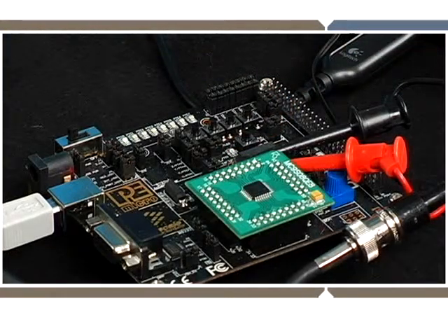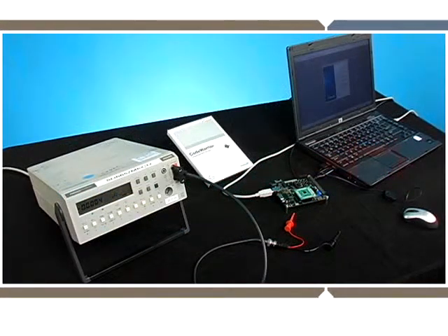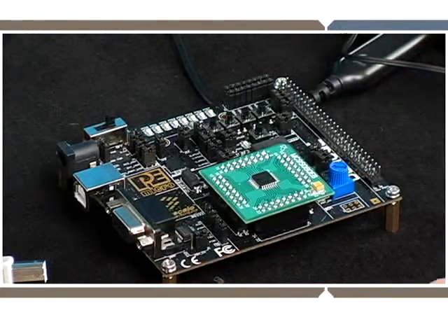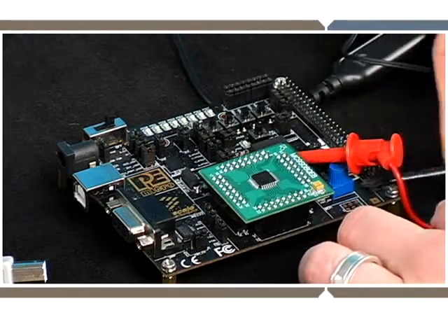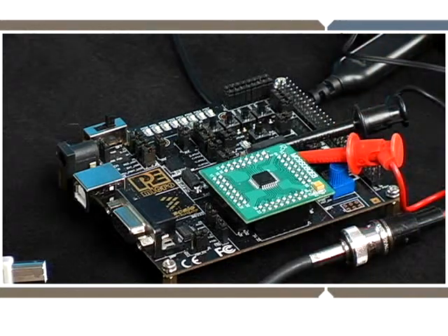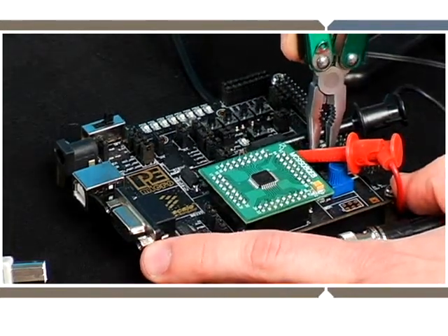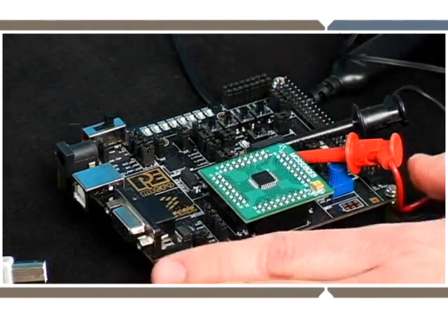So before getting started, let's get our board set up for the lab. My board is currently in the default out-of-the-box configuration. The first thing we'll need to do is remove jumper 17 and attach our digital multimeter to be able to measure average current consumption. Next, in order to use our external crystal oscillator, we'll need to remove the 2 jumpers at J20 on the board. These jumpers utilize a multiplexed function on the oscillator pins that we will not use during the lab.